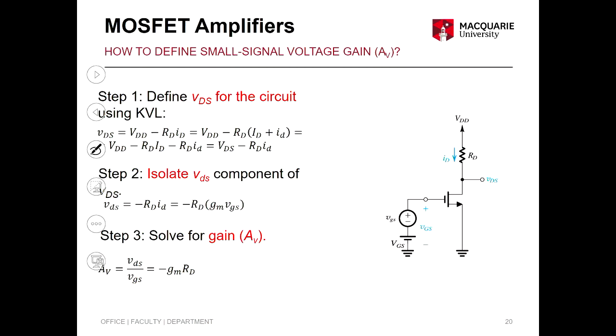Okay, so we talked about this briefly before. When we calculated any of these circuits, I said there's a DC part and there's an AC part. Now, if you have an AC part, you should be able to divide this circuit into two different levels. We call it large signal and small signal, which you might remember. So I try to isolate the DC because DC is fixed, right? And then I just focus on the AC signal. Then we call it the small signal model.